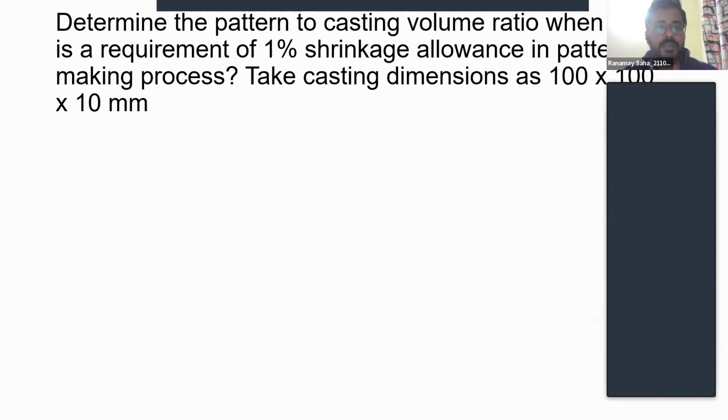Okay, so this is a question. Shrinkage allowance, you know, right? Yes, sir. Do you know which type of shrinkage requires the most attention, which type happens to be the highest shrinkage during the casting process, from the freezing temperature to room temperature? Yeah, so solidification shrinkage.